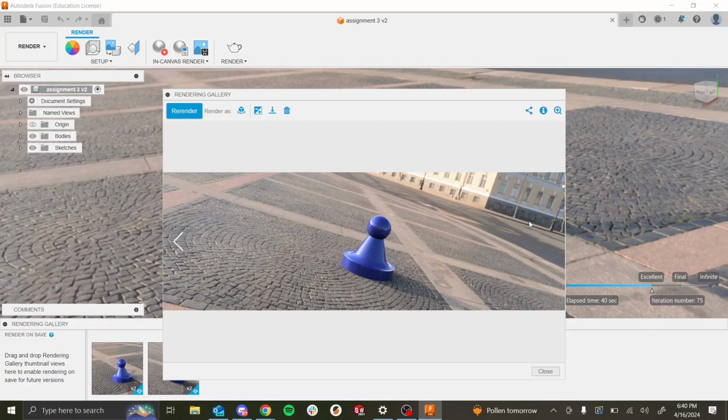So again, don't print super thin features, especially those on the build plate, because they are not super fun to use. Wait, I can actually just show you some examples because I'm doing these right now. So I'm going to run through some examples of final projects from last group and also point out some things that you shouldn't do because it'll make my life a lot easier and you'll have better prints in the end.